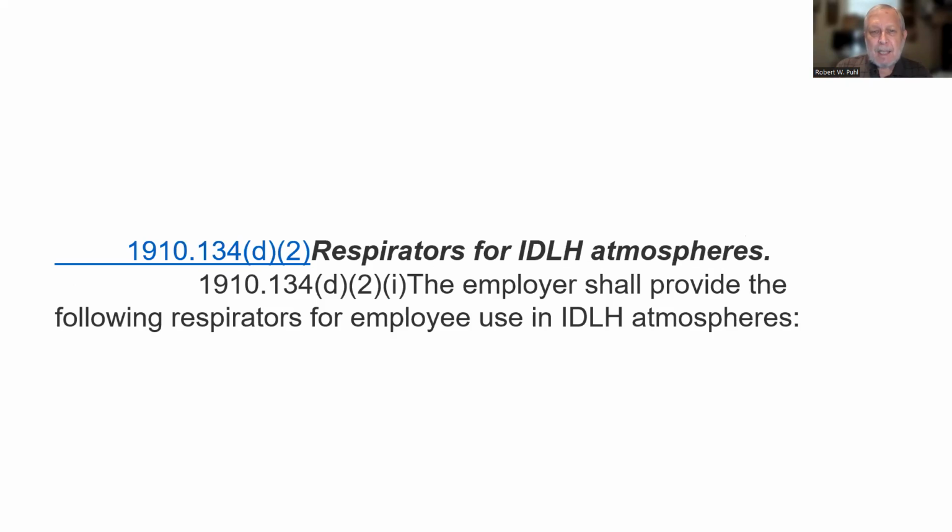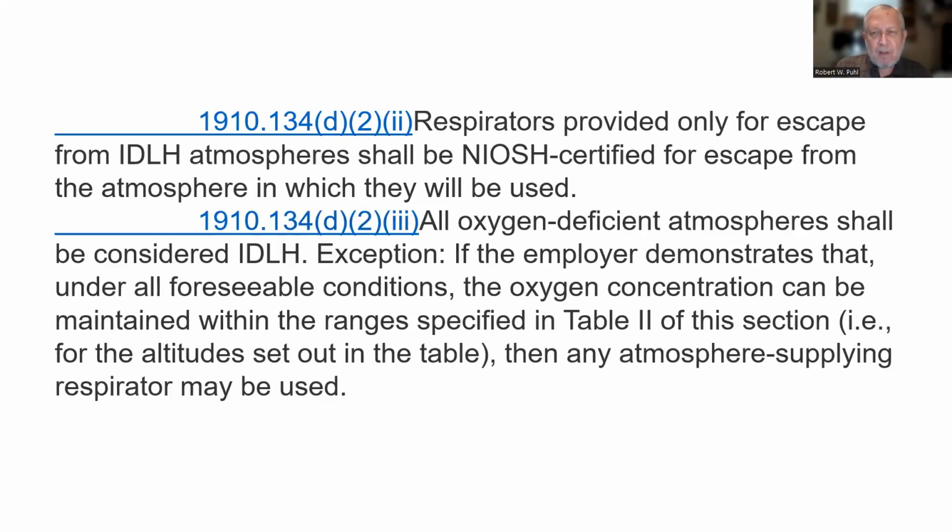Respirators for IDLH atmospheres. The employer shall provide the following respirators for employee use in IDLH atmospheres. Respirators provided only for escape from IDLH atmospheres shall be NIOSH certified for escape from the atmosphere in which they will be used. So in other words, an escape respirator for an IDLH atmosphere is only good for the atmosphere in which it'll be used, which makes sense.